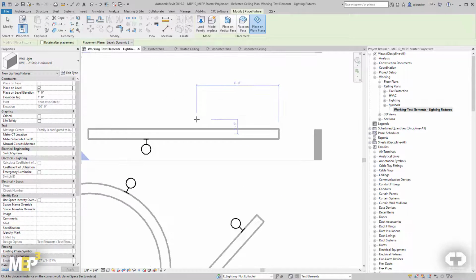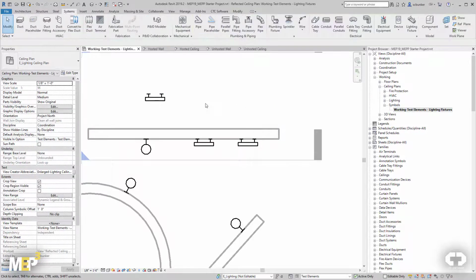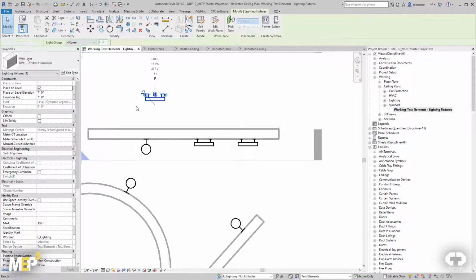This is because Revit generated the preview based on the instance parameter settings at the time the placement command was initiated. We changed the instance parameter settings, and the preview is no longer valid. After we place any instance, however, the preview will regenerate. Some fixtures behave this way, and some don't. If you find that you do not have a placement preview, it may be helpful to first place a throwaway instance, then continue to place your fixtures as needed, then go back and delete that first instance.